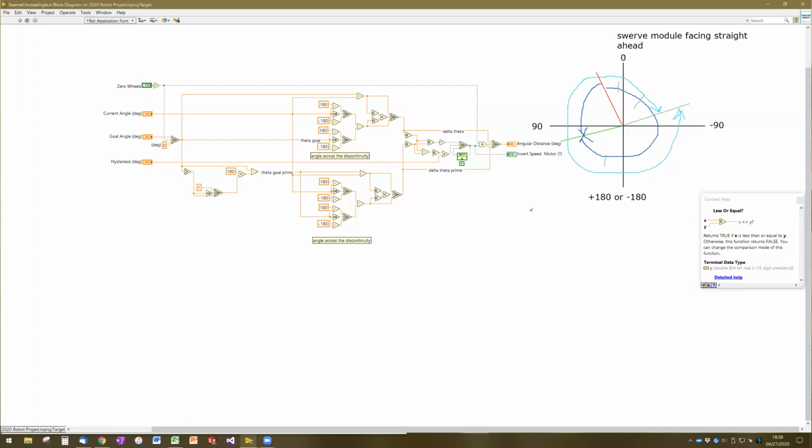And so you could end up in a situation where the wheel will bounce around between trying to get to the goal angle versus the opposite of that goal angle, and it's trying to get to that shortest route, and it'll just sit there oscillating back and forth and never actually get anywhere. And so we want to avoid that problem. Does that problem make sense to everyone as it's described? So does anyone have any thoughts on how we could mitigate this problem, how we could keep the wheel from having this behavior?